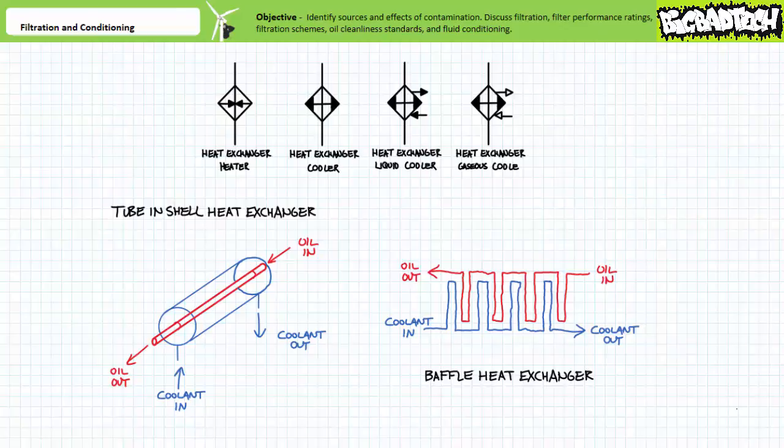Not only does the reservoir ensure a quantity of oil is readily available to the system, it also serves to cool liquid returning from the system and allow time for any particles to settle out and any entrained air to dissipate before the oil is again pumped up and circulated through the system. We'll examine reservoirs and hydraulic power units in greater detail in later lectures.